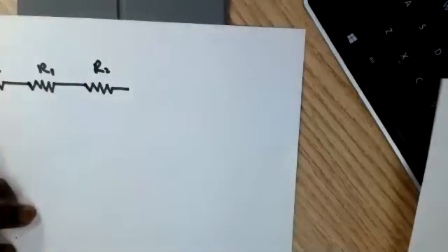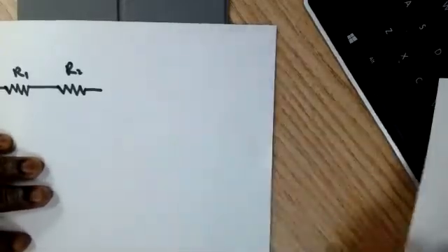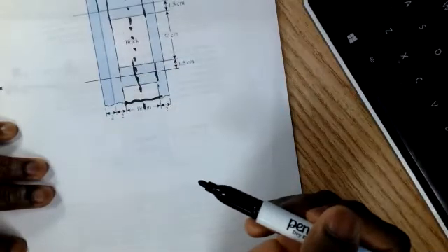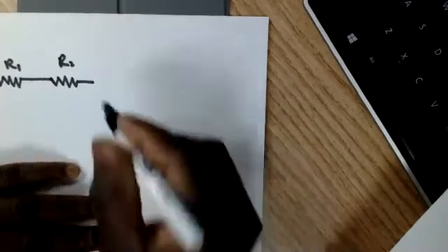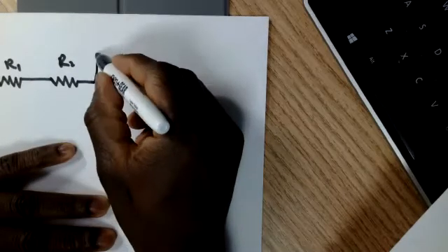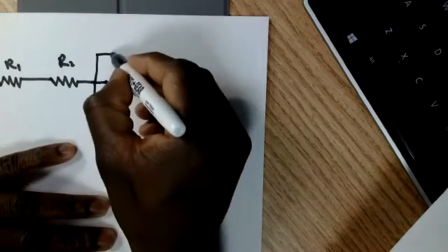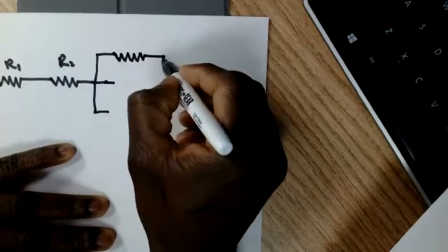So I'm just going to pick a region in the wall where we have a plaster, a brick, and then another plaster region, just so that we have that covered. If you multiply that by the rest of the portion of the wall, you get the same result. So this is going to split into three resistances.